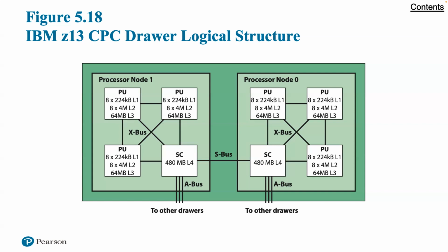The use of the L3 cache that is shared by 8 cores on a chip facilitates low-latency cross-processor cache line sharing and provides cache efficiency effects by the elimination of redundant lines, single copy, multiple users, which is not possible with private caches. Thus, there are efficiency gains by devoting a substantial portion of each PU chip to a shared L3 cache, as opposed to either increasing the size of the L2 cache or providing a private L3 cache for each core.